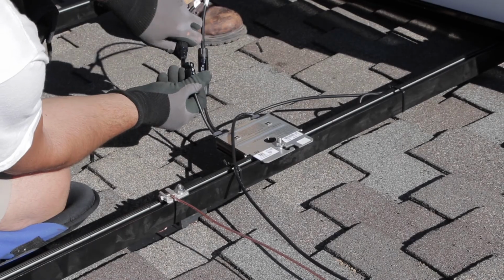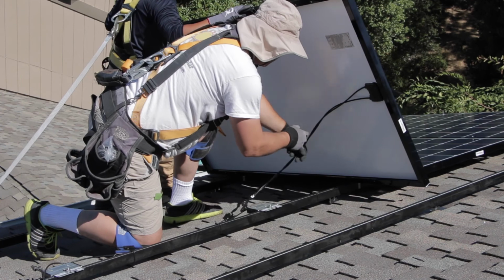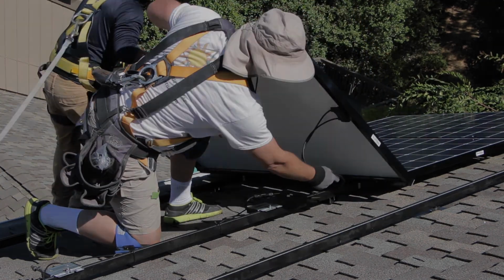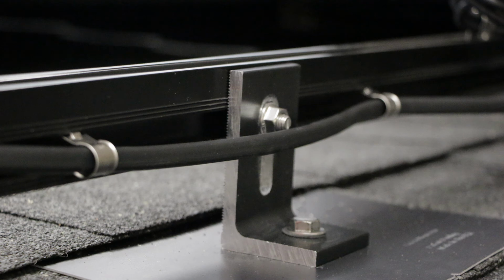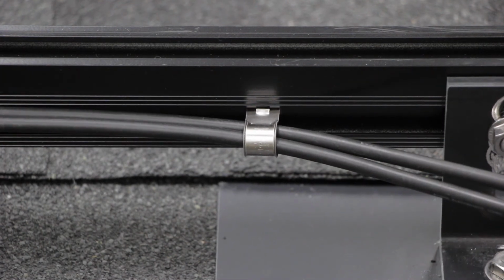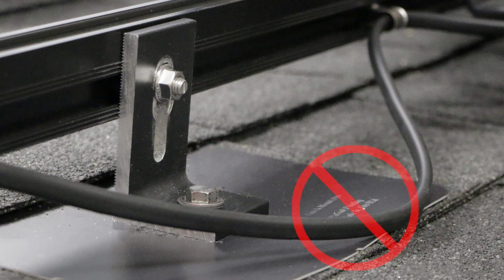As you lay down each module, make sure to connect the PV wires to any microinverters or optimizers you may be using and then connect them to the next module in the string. Keep the wires from sagging by clipping them to the QRail or to the module frame where necessary without pulling them too tight, since there will be ongoing thermal contraction and expansion. NEC requirements also stipulate a minimum bend radius, so tight coiling or bending is not advisable. In no case should wires be less than 2 inches from the roof surface.